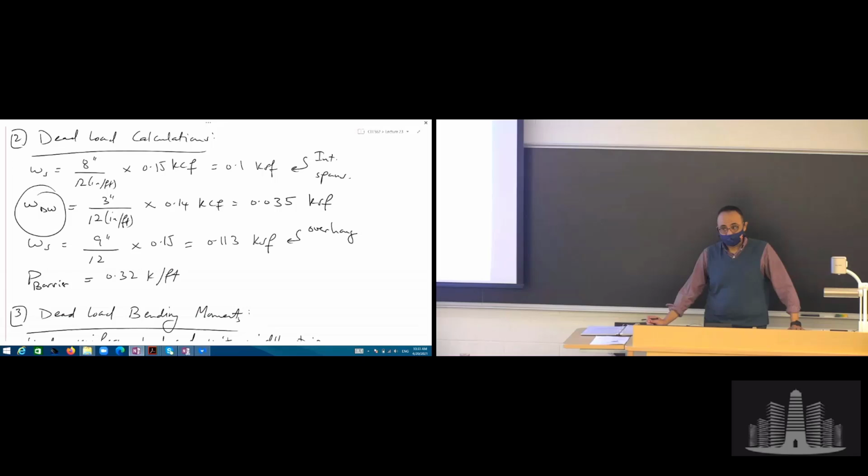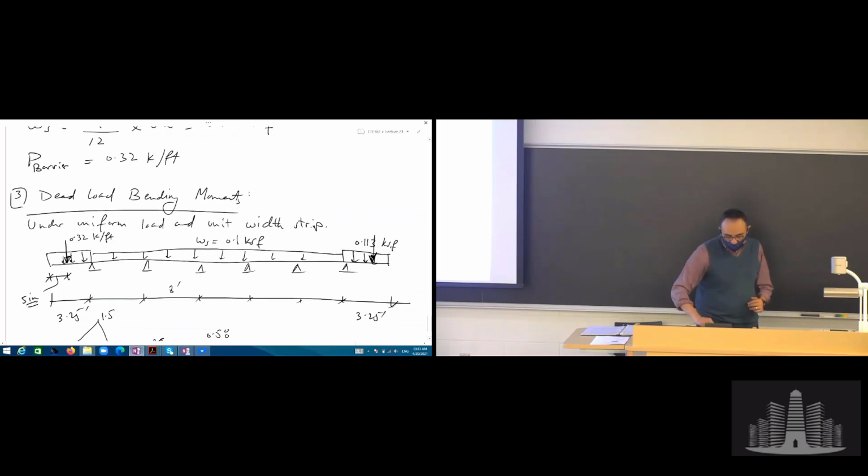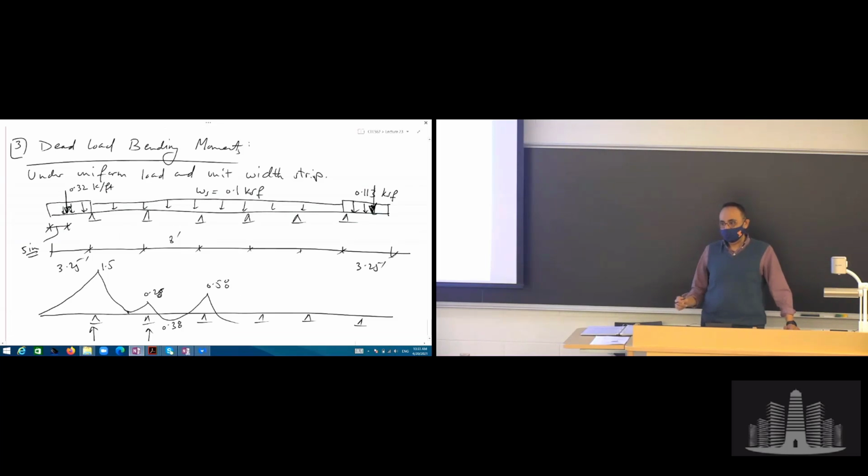During the construction process, so this will be provided like after the. Sure, it's going to be provided after, but now what I'm doing is that I'm calculating the dead load moment. This will be taken by the girder as the composite section. The wearing surface? So I don't have to design the deck for the wearing surface? Is that what you're saying? Eventually it's going to go to the girders, I understand, but in the load path from up there to the girders, it's going to be carried by the slab. Like the self-weight. I mean, really, it's nothing more than just another layer there, right? It's just on top of this, we have another layer there. So why did I neglect it here or ignore it?